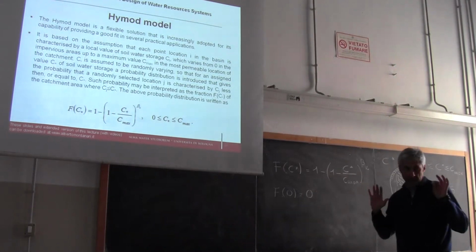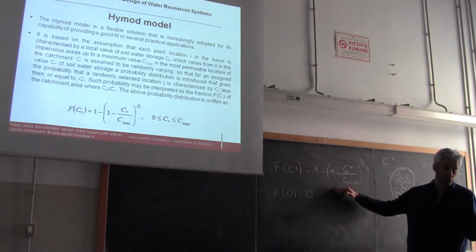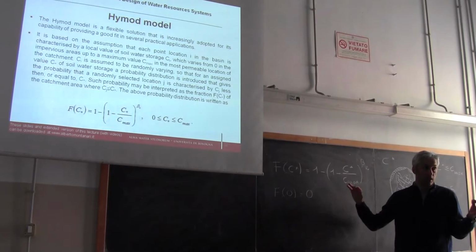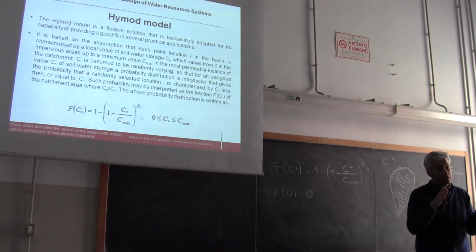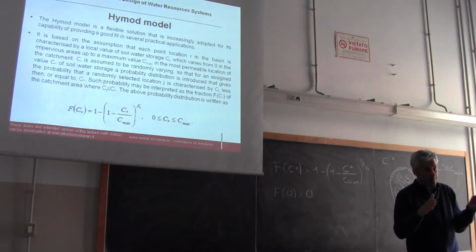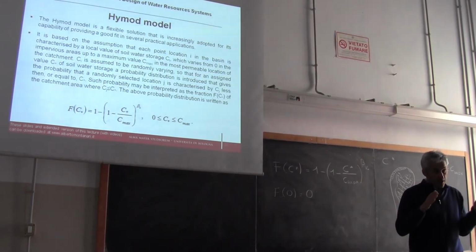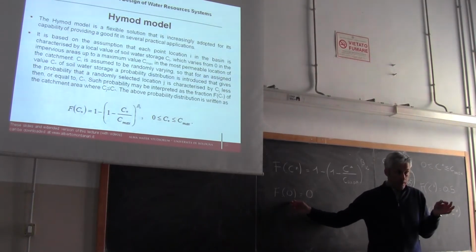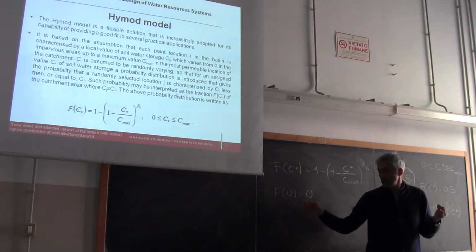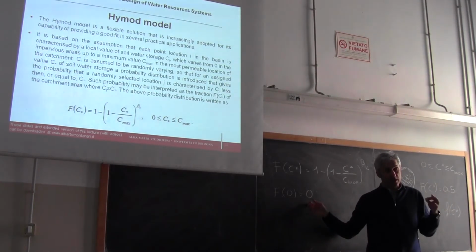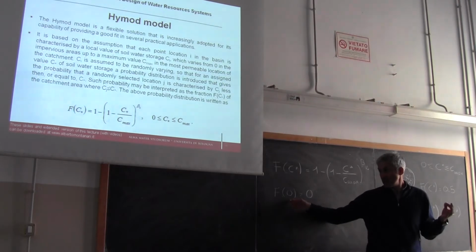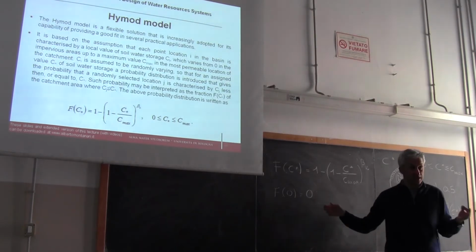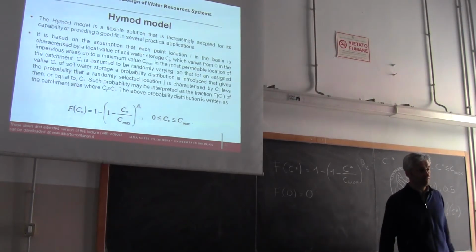Remember what this relationship gives you: in relative terms, the extension of the catchment area where storage is lower or equal than 0. Of course, it can't be other than 0 because storage cannot be negative. So the percentage of the area where storage is lower or equal to 0 is just 0. Okay?